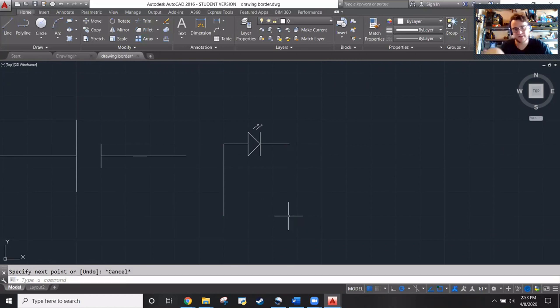So if I want it to be 3 grid lines long, as I'm drawing that line, I make sure it's perpendicular, and then I type in 1.5. And so that tells it how long to make that line, right? It'll just make it in whatever direction I go. So if I say 3, while I have my cursor over perpendicular to that original line, it'll make it 3 units long, perpendicular. Okay, so whack those 2 example lines I just showed.